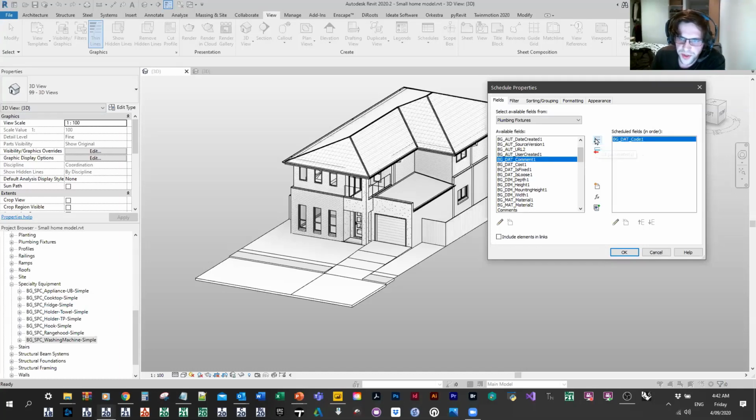I'm also going to get my description, which is a shared parameter in my case, that's also pushed into the description field. It's like a double up parameter. And a really important field, if anyone's not aware of it, is count. Count is like a default parameter that comes with most schedules that essentially does a tally for you. And this is pretty much the backbone to generating a quantity takeoff. I'm just going to make the schedule at this point, just to show you what I get.